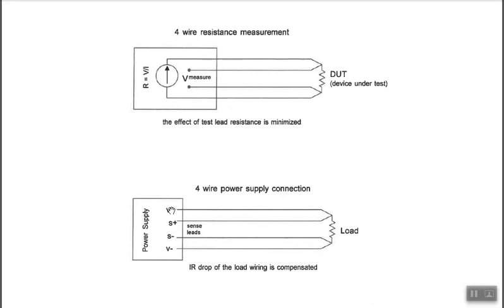It's going to crank the output as high as it can to try to get voltage to show up on the sense leads. So keep that in mind. If you have a power supply output that has sense S plus and S minus, S plus has to be connected to V plus. Especially if you don't connect it out here, if you're not planning to use the 4-wire connection to your load, you better then jumper it from here to here and jumper it from here to here.